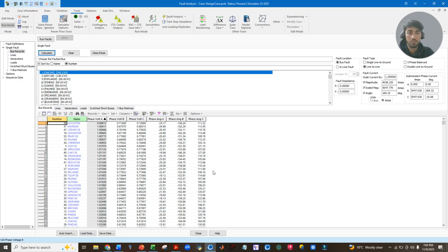Again, it's an angle deviation, and then we have to conduct double line to ground fault. So we have to select a maximum value, I think it was for three-phase balanced, and it is almost 5.8 kiloamperes. So we have to select on the basis of this value.